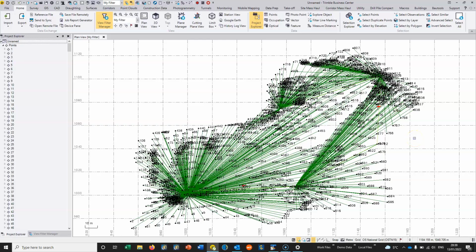So often when surveyors are completing surveys, coordinates, particularly Ordnance Survey coordinates, might not be immediately available to them. And the survey will therefore, first of all, be conducted at an entirely local site. And as coordinates are available for some of the stations, then the survey can be recomputed using those stations.